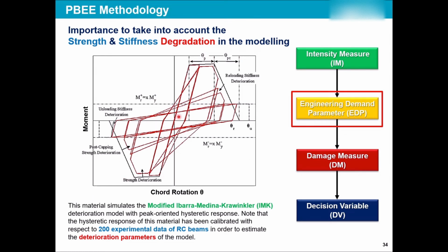In that session, which is dedicated to nonlinear analysis, we will talk about these in more detail, and the whole fact is that when you have the hysteresis behavior, you can consider the strength and stiffness degradation. Anyhow, materials lose their strength. As you can see, this is the first cycle. The second cycle has less strength, less stiffness. The third cycle, the same thing, less stiffness and less strength, and we carry on until full failure.